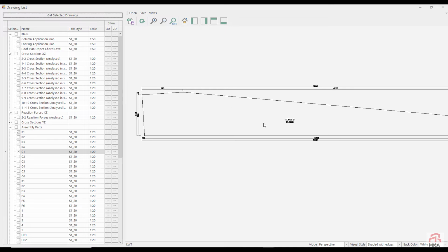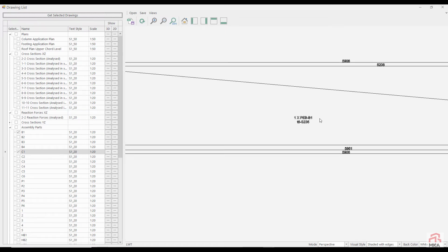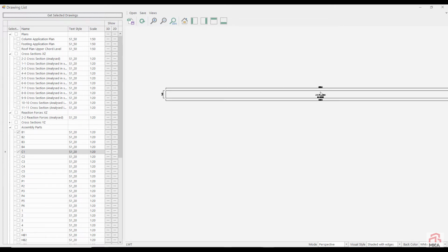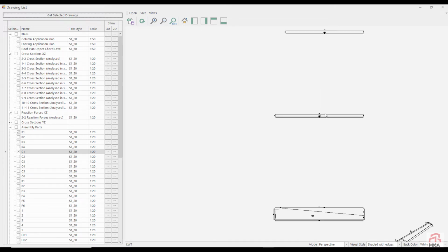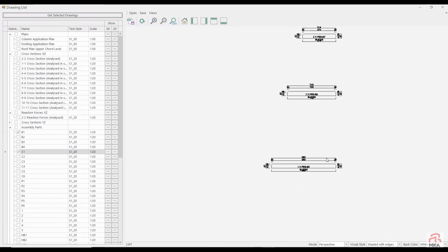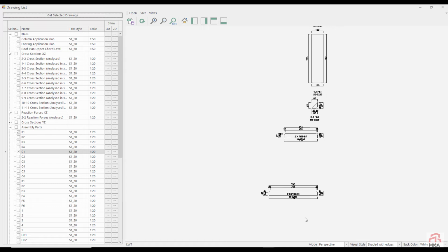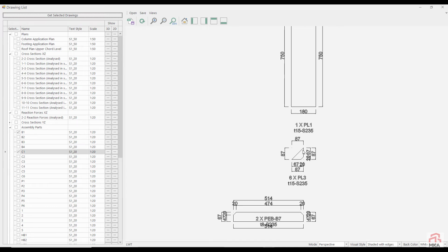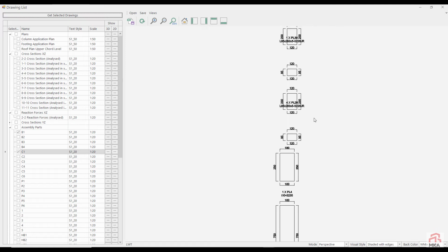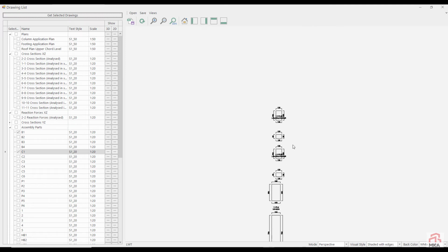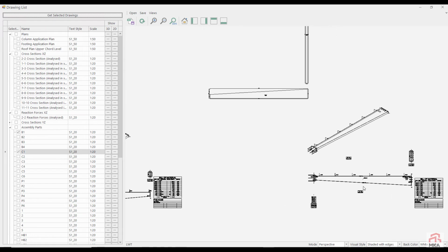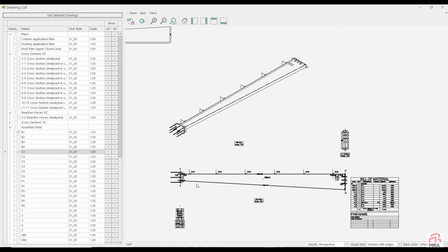One of these will be cut for this assembly part. This piece was already on the plate cut list. Then the lower and upper flange of this rafter. Other stiffener plates. These are the plates that come from the bolted connections. This assembly part can be obtained when the plates are cut and welded in this way. This is our C1 column assembly part.